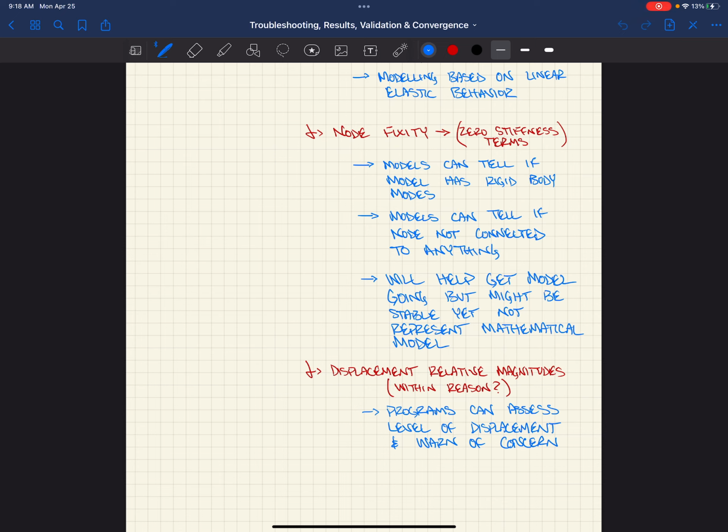Let's say that node is fixed, then you have another member coming into that pin connection. Yeah, I mean, if you had everything coming in and you released all the members framing into that node, and then you decided to fix the node to keep the stability, then that node shouldn't get any moment from any of those members framing into it. And it would represent essentially a pin. Which would be a weird way to do it, but yeah, it'd be a creative way to do it.